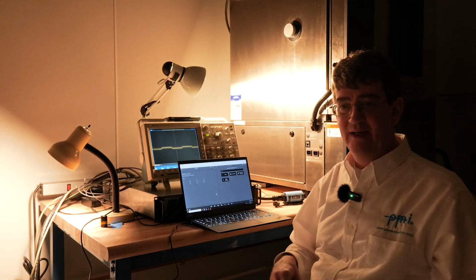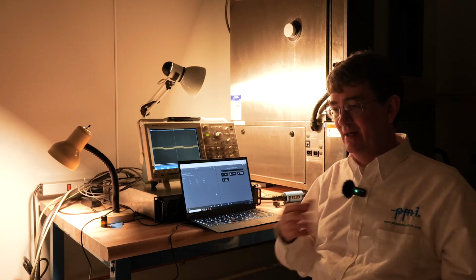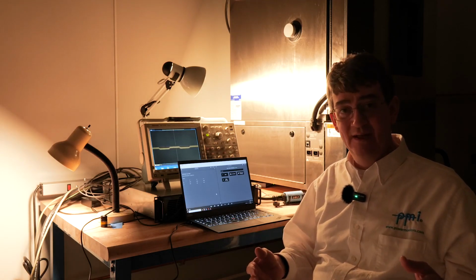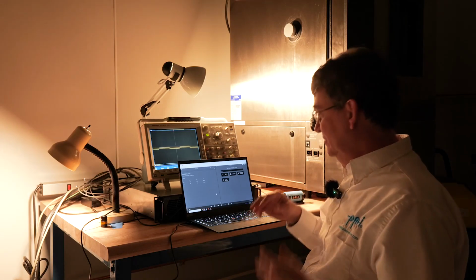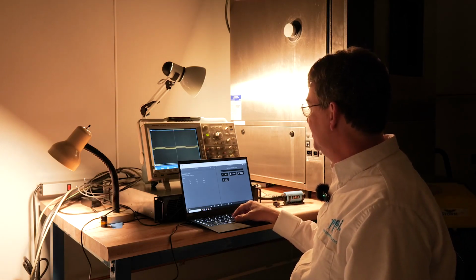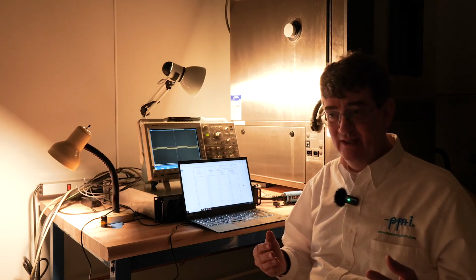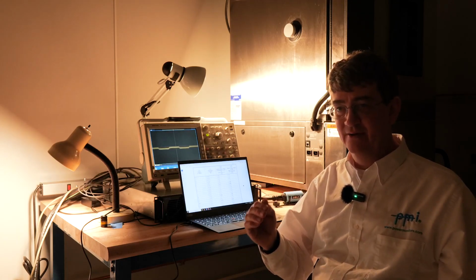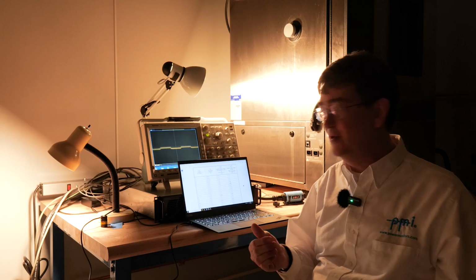The flicker readings are slow because the standard calls for a 10-minute reading. So it takes a minimum of 10 minutes to get a new value once the level has changed per the standard. Now, we're going to go through the conformance test that is in the standard. And IEEE 1453 gives a list of 29 voltage change patterns, and each of these should read a PST of 1 plus or minus 0.05.